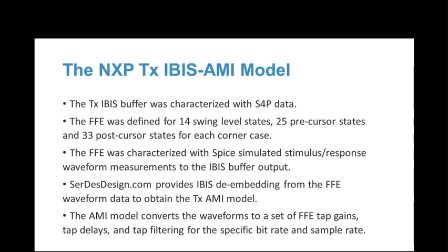The AMI model converts the waveforms to a set of FFE tap gains, tap delays, and tap filtering for the specific bit rate and sample rate used in the simulation. The SerDesDesign.com channel simulator automatically de-embedded the transmit IBIS buffer characteristics from the transmit black box data to derive the AMI characteristics.